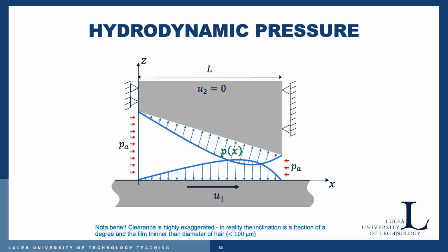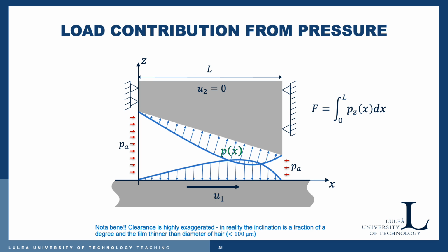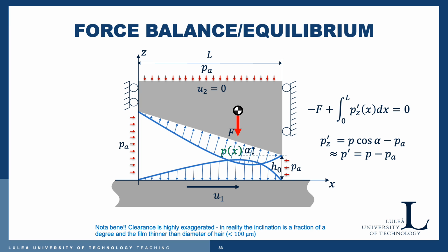Now, this is the fourth part of the second video lecture on the introduction and underlying theory, and here you will learn about different constituents of the Reynolds equations, such as the film thickness equation, compressibility, pressure viscosity relationship, and a little bit about lubricant rheology.